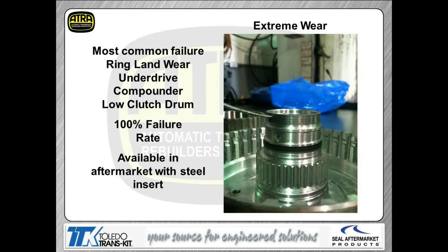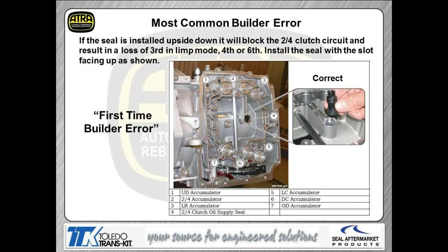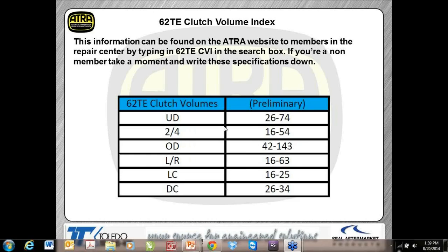Now, to avoid, like we were saying before, that double swap shift on the 6-4 downshift, they use that 4th gear prime ratio, and that only requires turning off the overdrive clutch while we're bringing on the underdrive clutch. So we only have two components to worry about there rather than a double swap like on the other shifts.